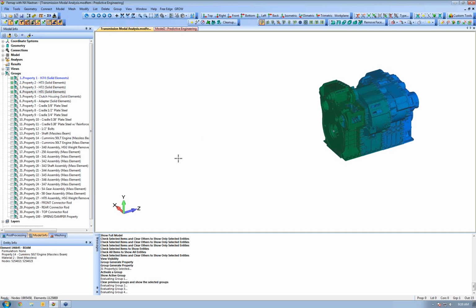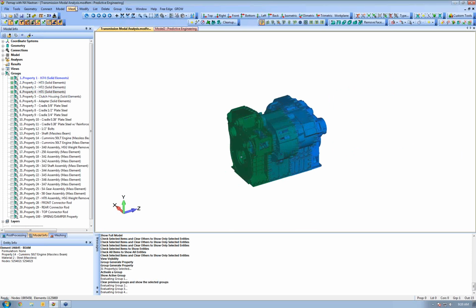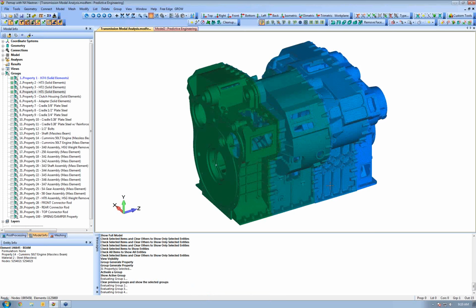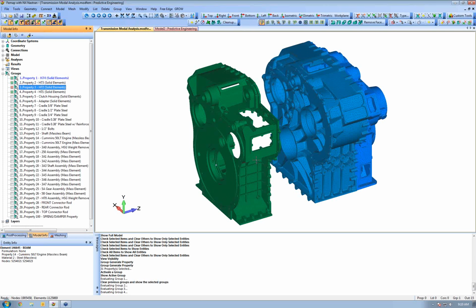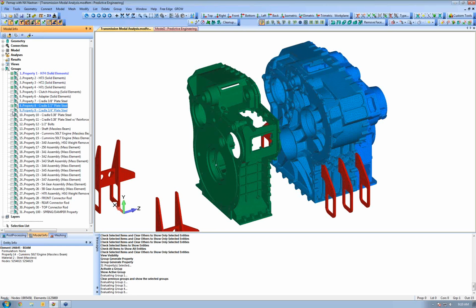It's like you would say a very large CAD model. You're only working with a subset of the model at any one time. And this is the smaller version. We actually have another version that's 3 million nodes, and it's nonlinear contact, because we're doing bolt preload and everything, and it runs in about an hour. So the performance is not bad. That's the advantage of using all the blanking in groups.